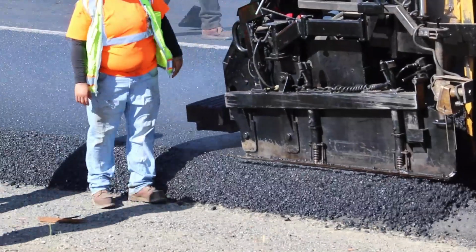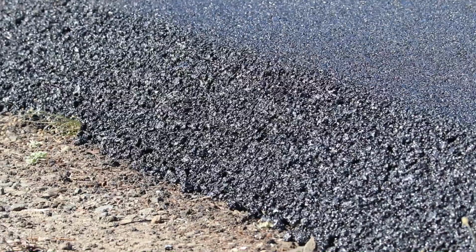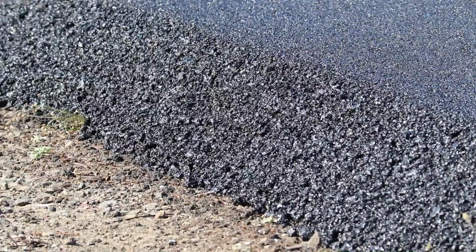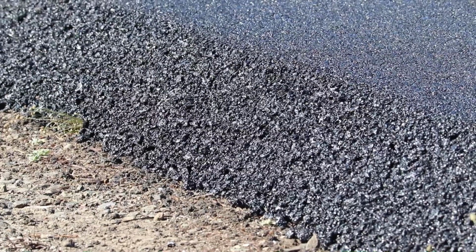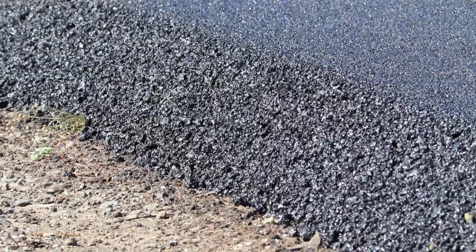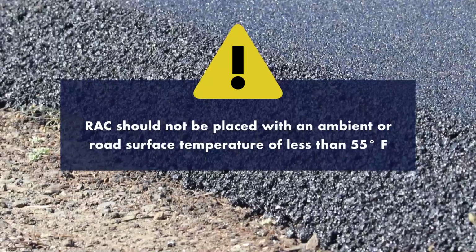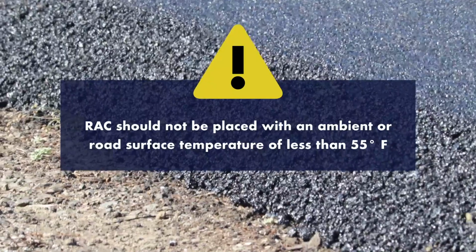The paver should be equipped with a fully operational screed leveling device. RAC mixes and laydown temperatures should be monitored using infrared and stab thermometers. These devices should be calibrated on a regular basis. RAC should not be placed with an ambient or road surface temperature of less than 55 degrees Fahrenheit.